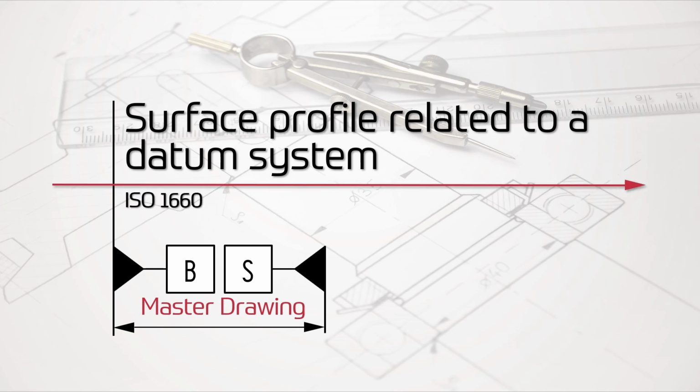The surface profile related to datum system belongs to the group of the location tolerances, which effectively control form, orientation and also the position of the tolerance feature. In this video I will explain how the tolerance zone is defined and how the deviation is calculated according to the ISO GPS standard.